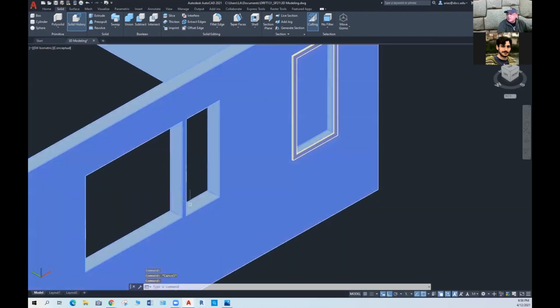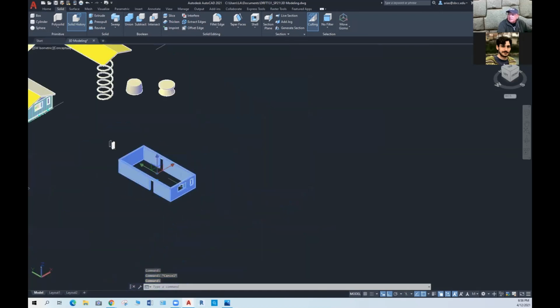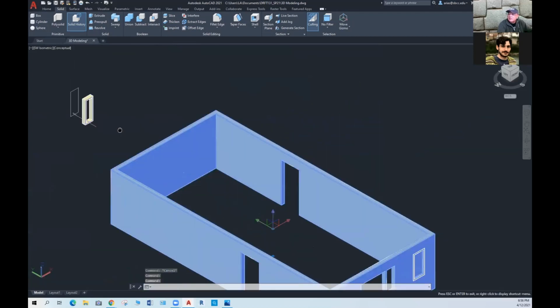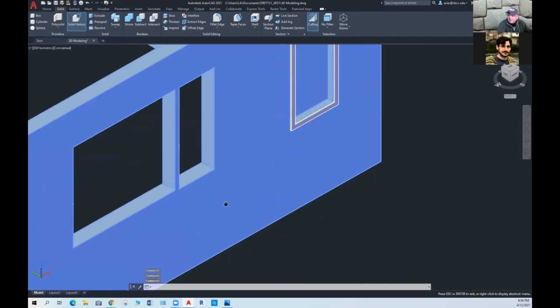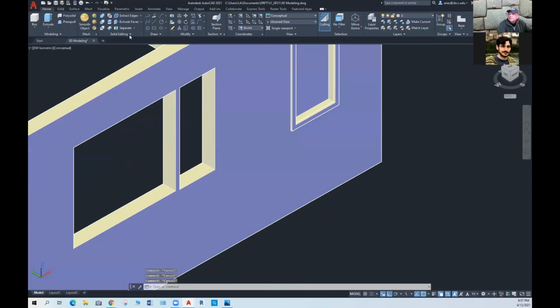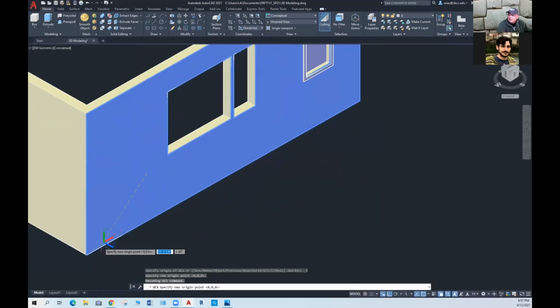And the same as we, if we have a mullion like this, and remember that we created this element to create the mullions on the side. So all of the elements of this particular building could have different materials. So let me do one here. 3-point UCS. Let's place the UCS right here. 1, 2.